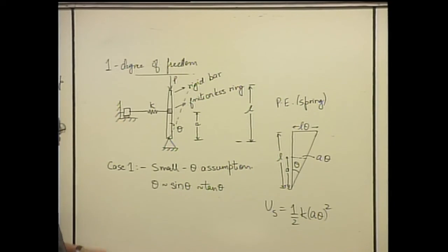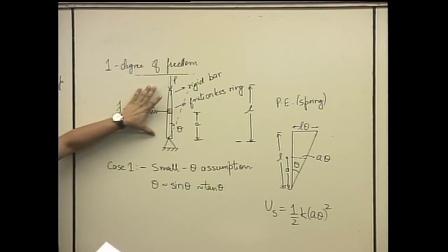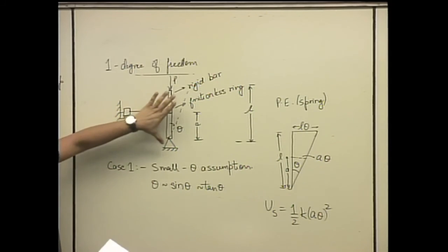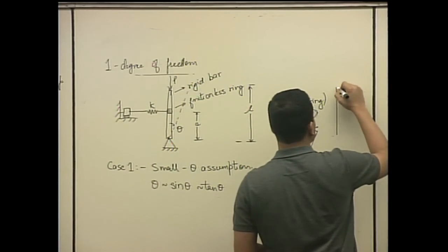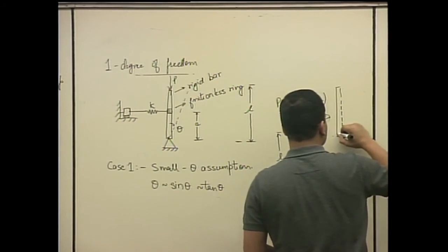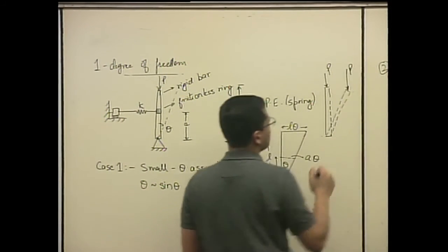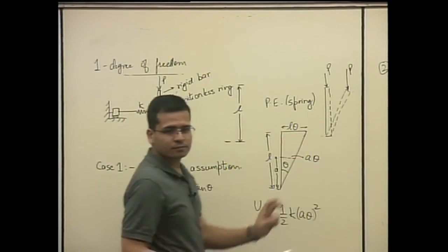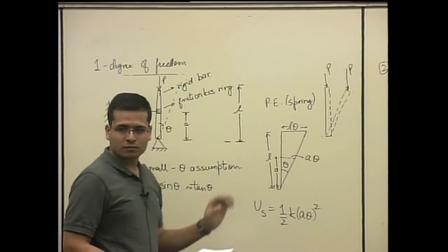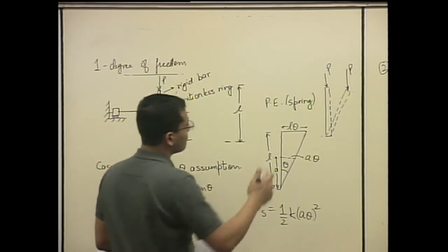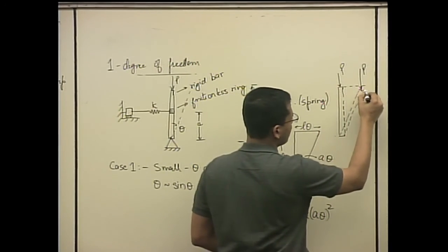And what are the characteristics of the P force? Let's assume that it doesn't move with the deformation. So let's say this is the undeformed state, then in the deformed state P was applied like this and P is applied like this here. So this is a conservative force, right? I can define a potential energy due to this externally applied conservative load, right? And for potential energy, I need to define the initial and the final states.